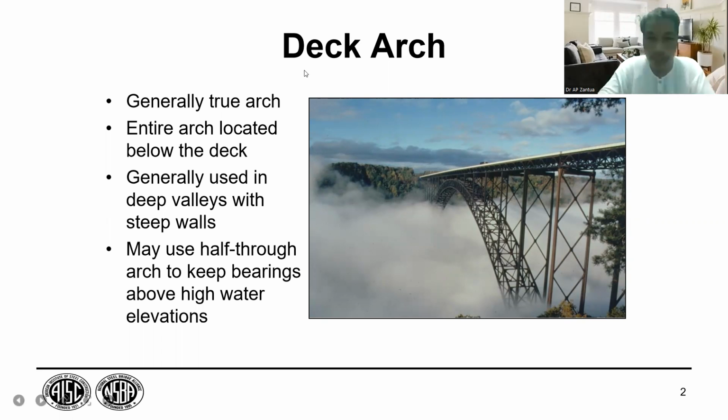So, deck arch. Generally true arch, entire arch located below the deck, generally used in deep valleys with steep walls. May use half-through arch to keep bearings above high water elevations. This is the general description of a deck type of arch bridge.